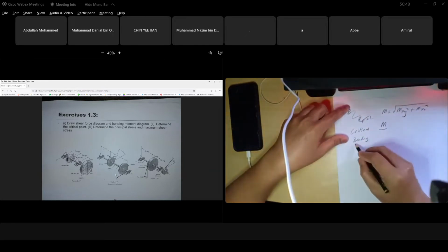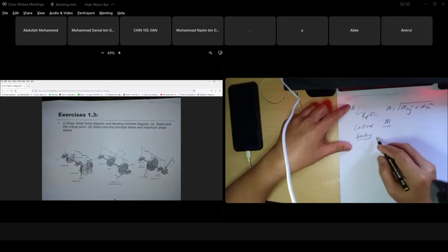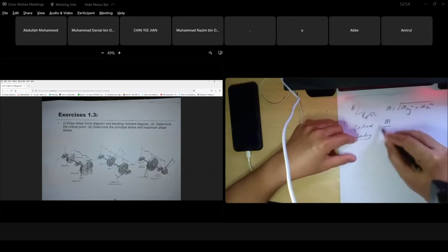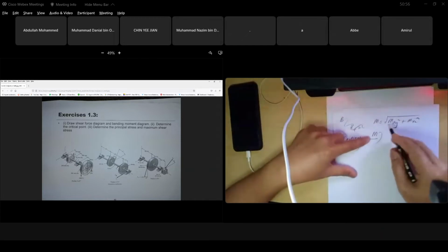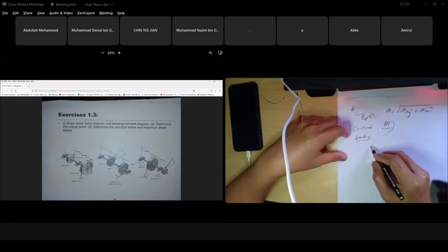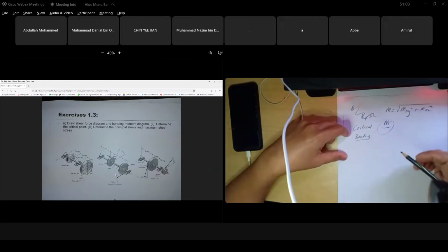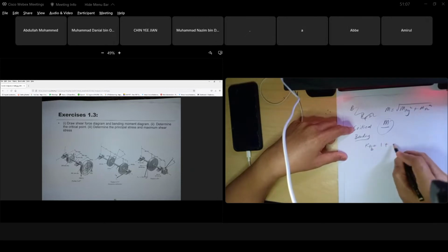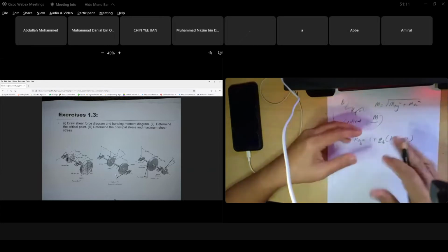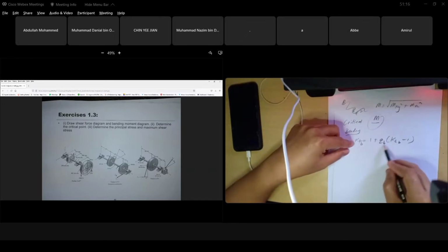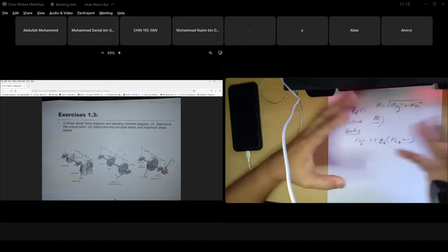So for bending, at that critical point, we know the value of the moment there. If we have two planes, we combine them; if one plane, just one. If we have moment, we have bending, and for bending we need KF. KF bending equals 1 plus q bending times (Kt bending minus 1). You have to know this. KF bending is the fatigue stress concentration factor, and q is the notch sensitivity based on bending. Bending and axial are the same.